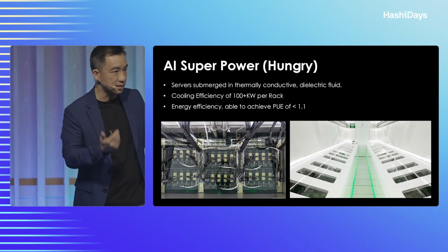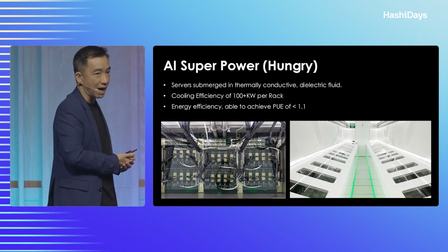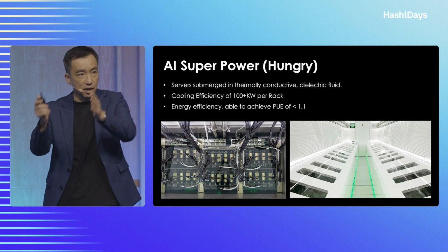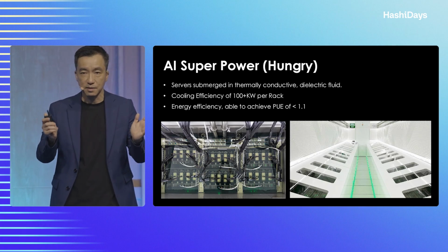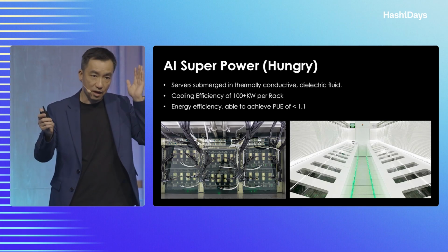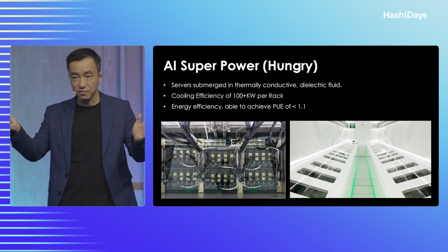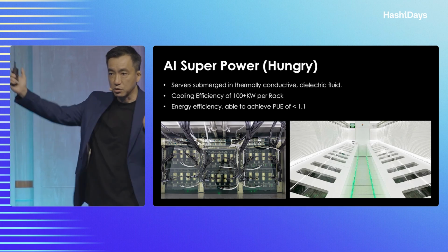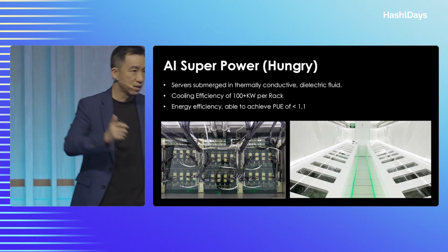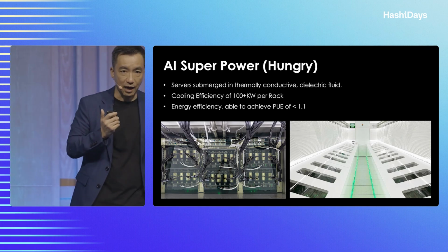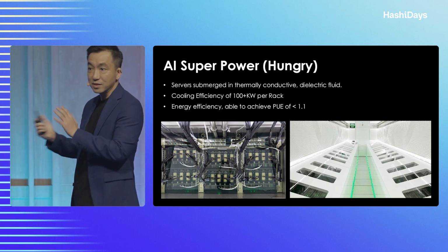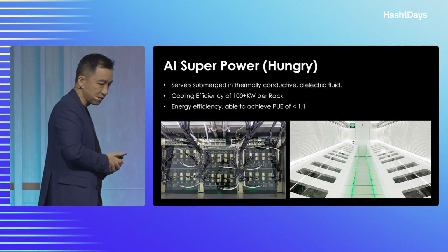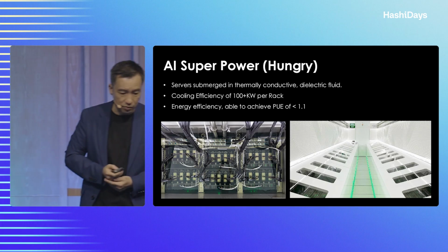For those who are not familiar with the data center space, we have this thing called PUE. For every kilowatt of power consumed, how much goes into computing and how much goes into cooling. So for typical data centers, the Green Mark guideline is 1.3. That means 100% used for computing, 30% for other stuff. The goal is to keep it as small as possible. Direct-to-chip and immersion cooling help us bring PUE down to less than 1.1. For information, most hyperscalers are doing PUE of 1.1 something, 1.15, 1.2, below 1.2. That's the standard for hyperscalers. So that's really the challenge for cooling.